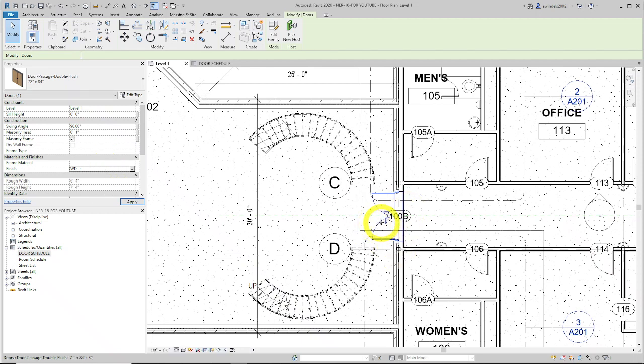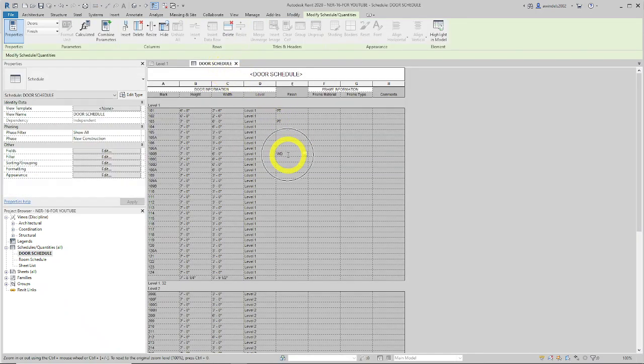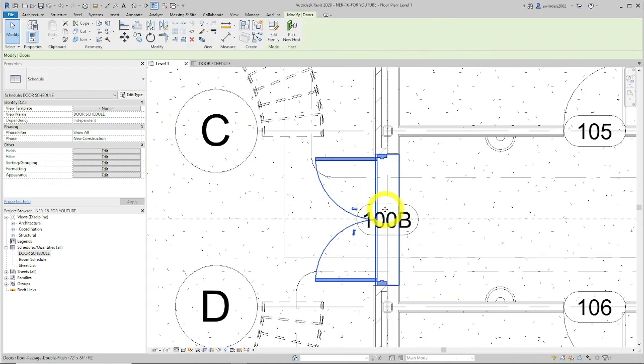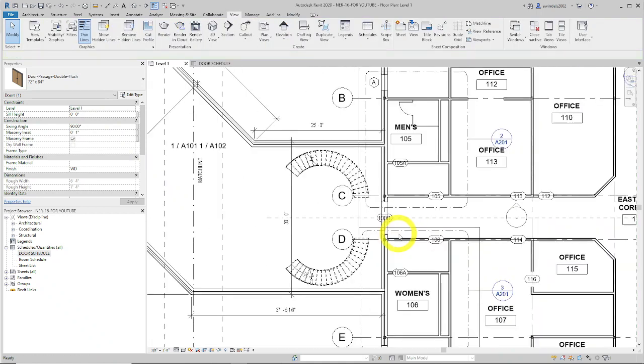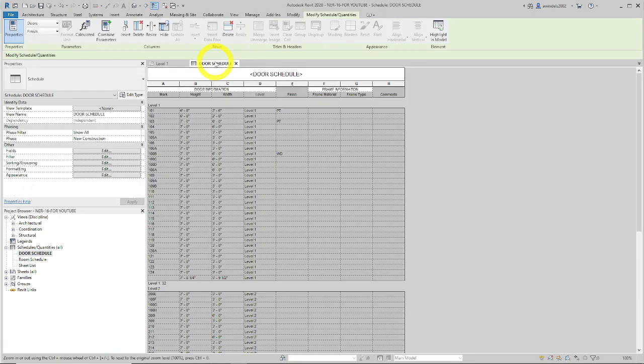So I have this door selected first, and I change the properties. Now if I go back to the door schedule, they're going to be interlinked. So this updated, I can update it here or graphically. That's a very key thing to get in this part between the database of the actual component and the schedule you made for said doors here. So that's the point of that.